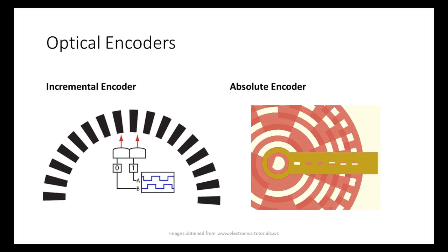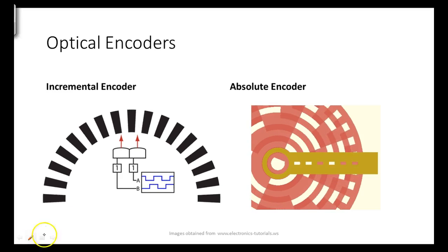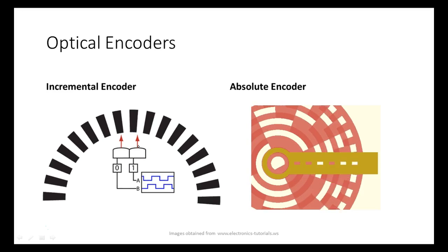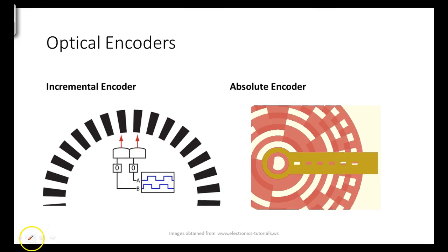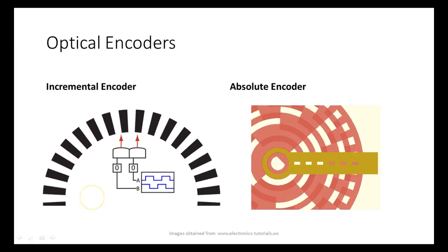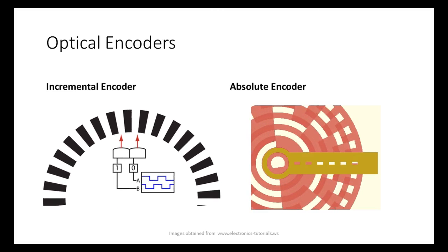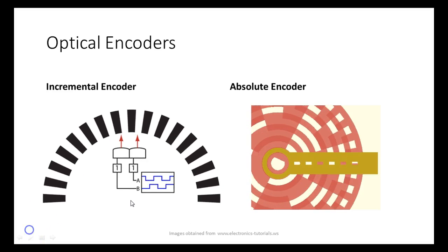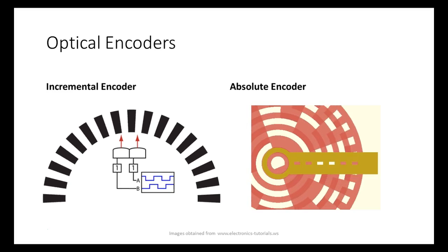And then sometimes they'll make one index mark for every revolution. So with an incremental encoder, we could get one pulse per revolution too, right? The robots usually have that. We'll go over there and look at it. So we can see the incremental encoders on the robot and counters and everything.